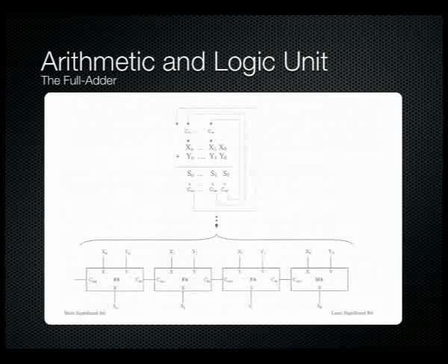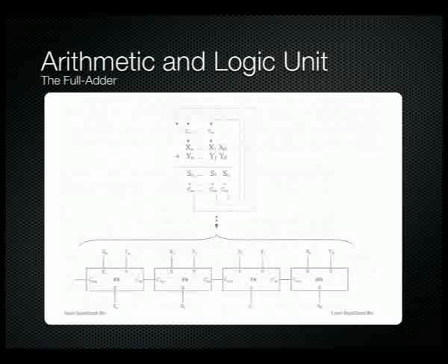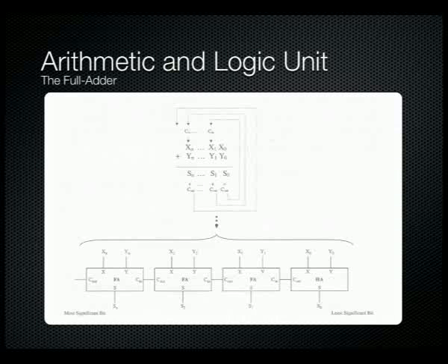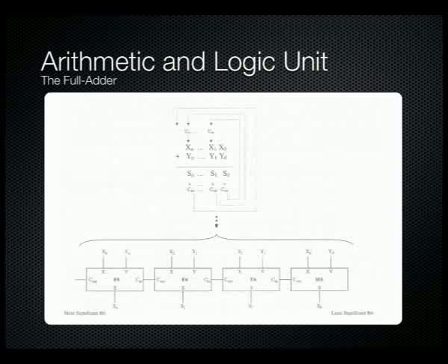So it's not a very efficient way of doing it, but what they do these days when it comes to doing addition is they have carry look-ahead circuitry, so we can predict beforehand what the carry bits are going to be. So on one clock cycle we can predict what all the carries are going to be, and then on the next clock cycle pass all those carries down to the addition stages and simply add them. In a couple of clock cycles we can effectively do the whole addition instead of having to wait for that carry bit to ripple through.